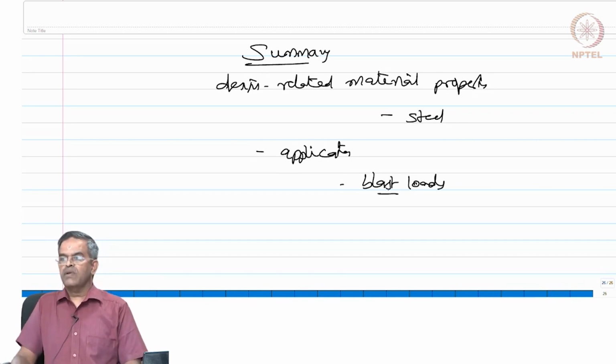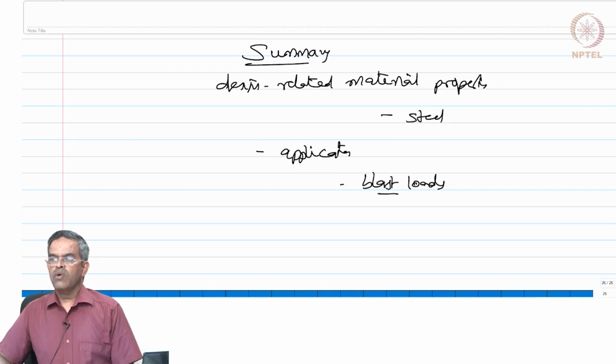So, I think this content will help you to know more about the variations in material characteristics, especially steel, when you look for its application which demands large deformations from the material side, because structural system undergoes large displacement because of its either form dominance or because of the rate of strain of the load coming larger on the material, which is a practice in case of blast loads and impact loads.